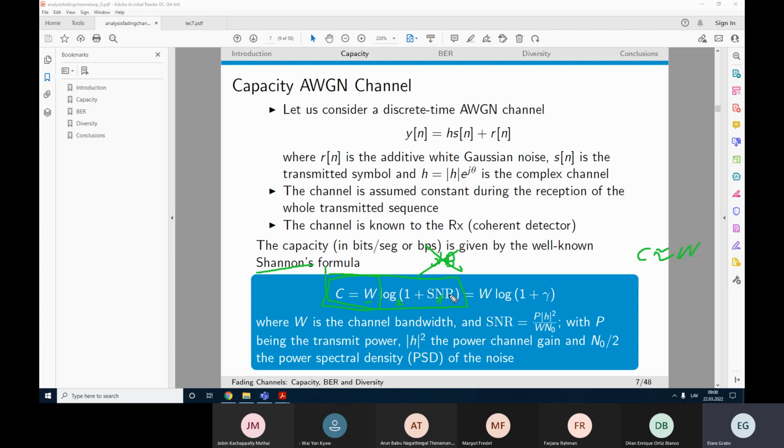However, often, as you imagine, SNR is smaller than 1. That means that the signal is weaker than noise. For that reason, we are not going to get 2 in these brackets, and the logarithm result is not going to be 1. It's going to be smaller than 1. And accordingly, the capacity will be smaller than the bandwidth. So that's what's happening because of this signal to noise ratio.